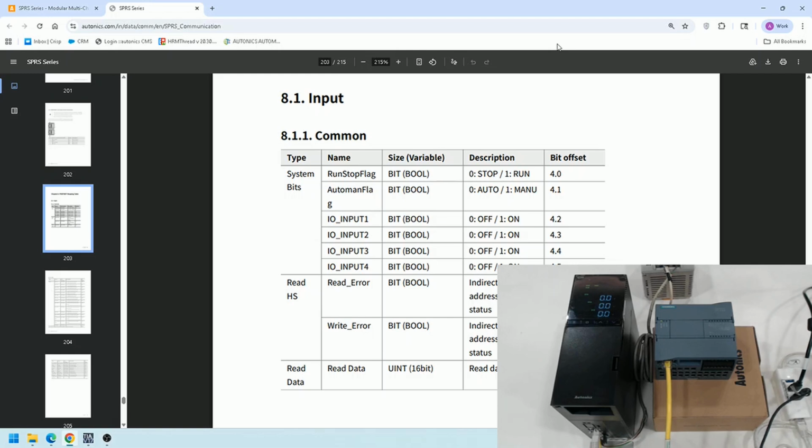So parameters which are for configuration purpose, you want to set the 4 modules in which mode: 1P1, 1P2, 2P1, 3P1, vice versa. That configuration we can do through Profinet communication, as well as we can set the current limit, we can set the voltage alarm limits. So all the configuration things that have to be done in the control module, we can do from Profinet communication. How to do that we are going to see in this video now.